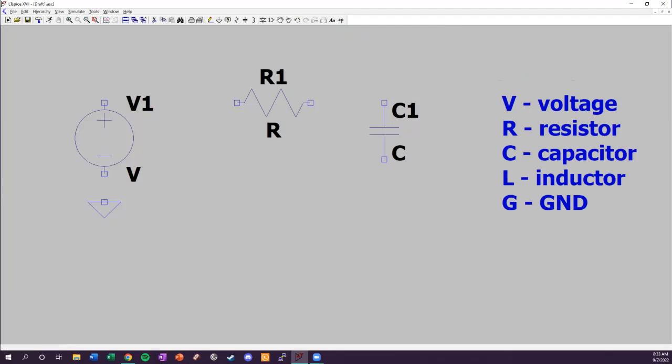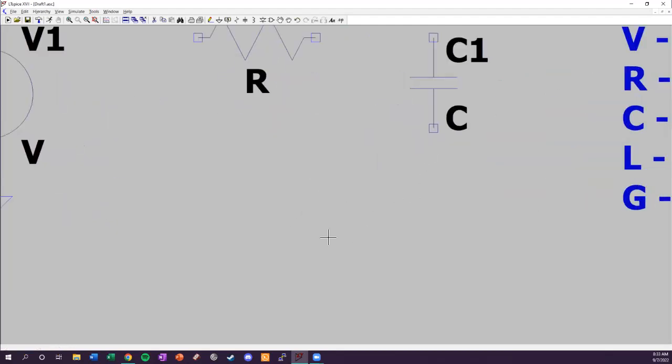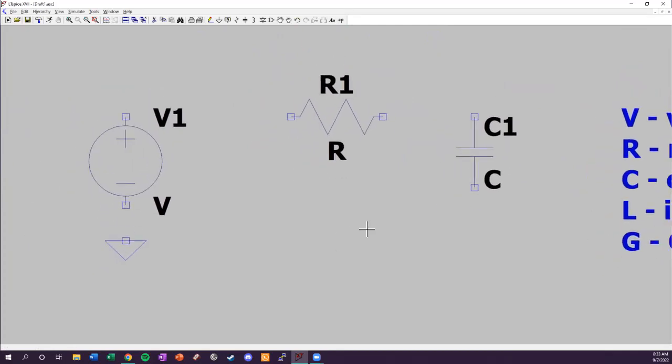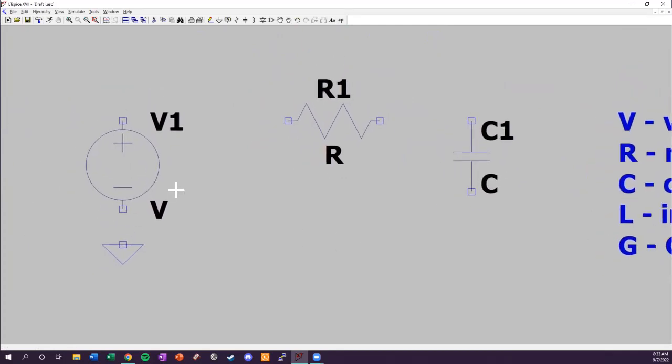All right, sweet. So now you have this simple looking circuit over here. And we actually want to play some more. So if you're on Windows, you should see a pencil toolbar up here. If you're on Mac, just two-finger right click, go to draft, draw a wire. From there, LTSpice works such that you can connect box to box, essentially something like this.